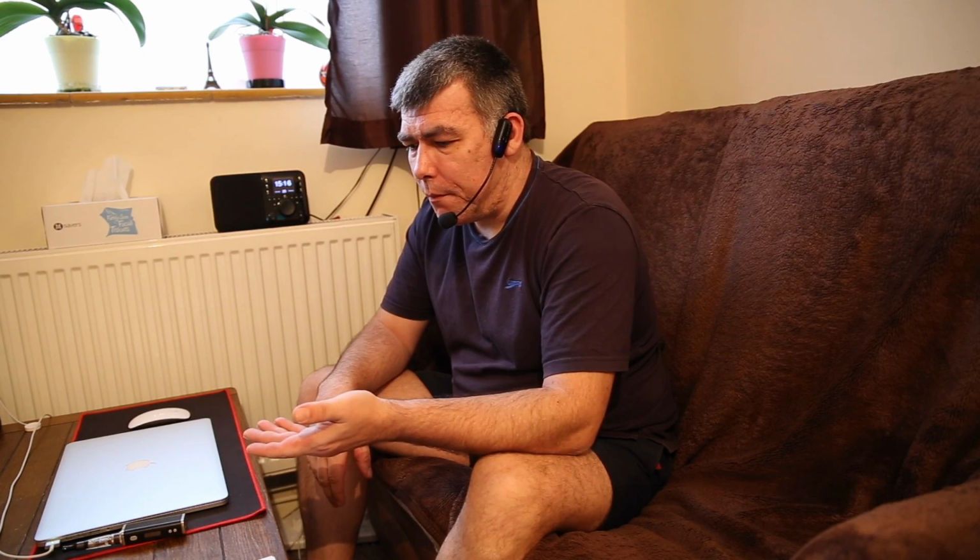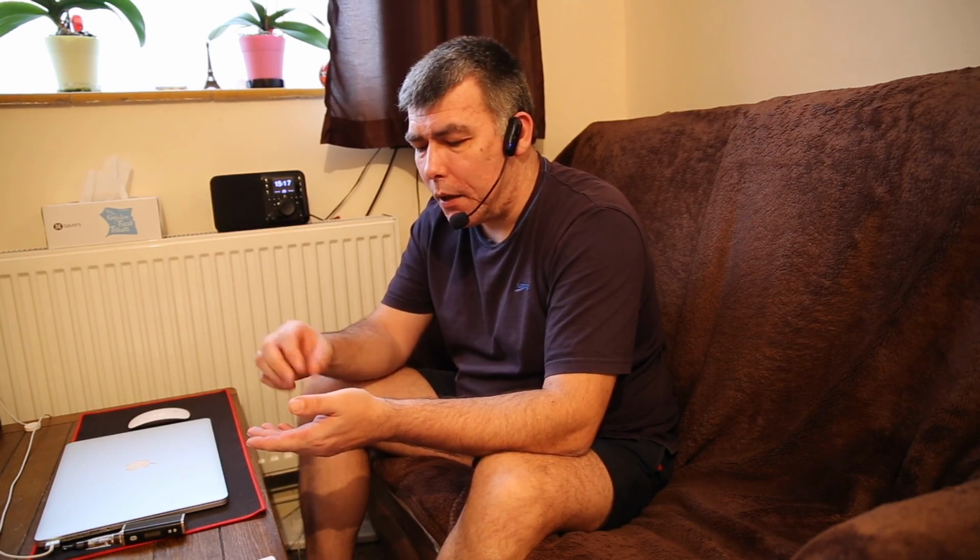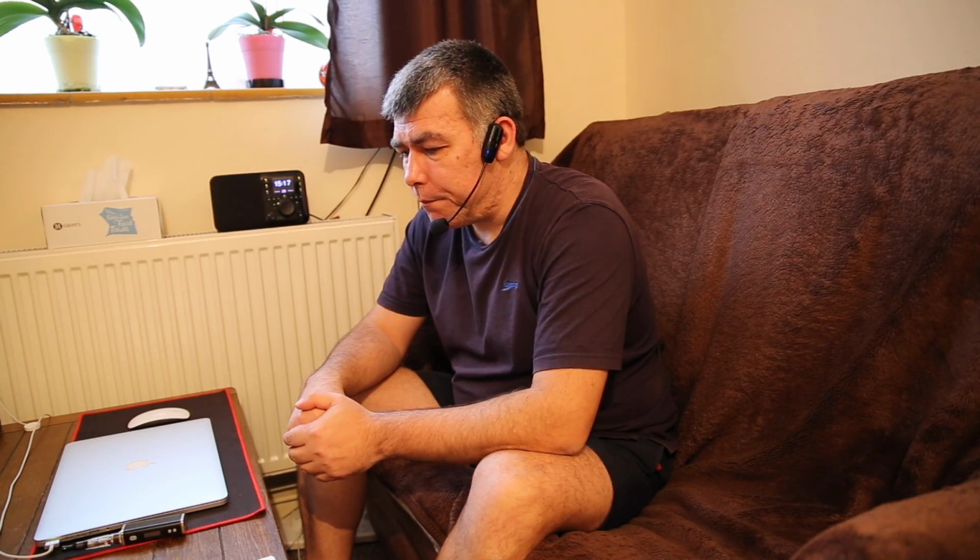When I'm doing graphics repair on a motherboard, over the graphic chip is the keyboard. The keyboard is metal. I'm using this kind of compound to redirect the heat from the back of the graphic chip to the back of the keyboard. So every time it's a good idea if you can get rid of the heat and keep the temperature lower on your desktop or laptop. It's not a bad idea.